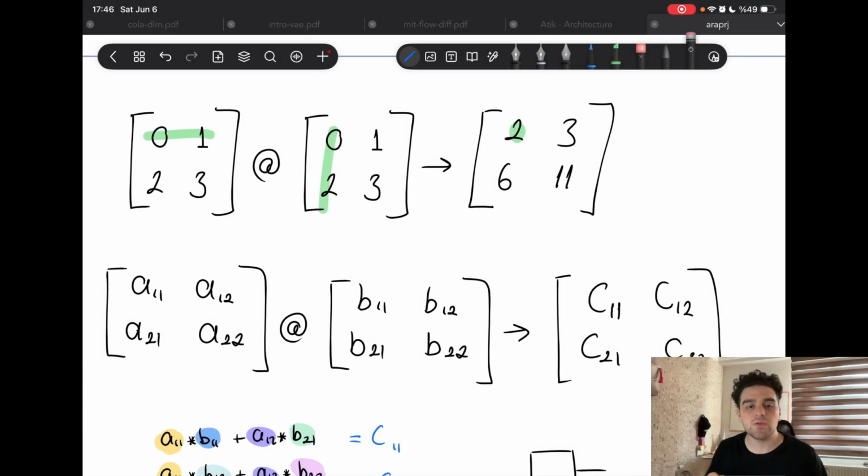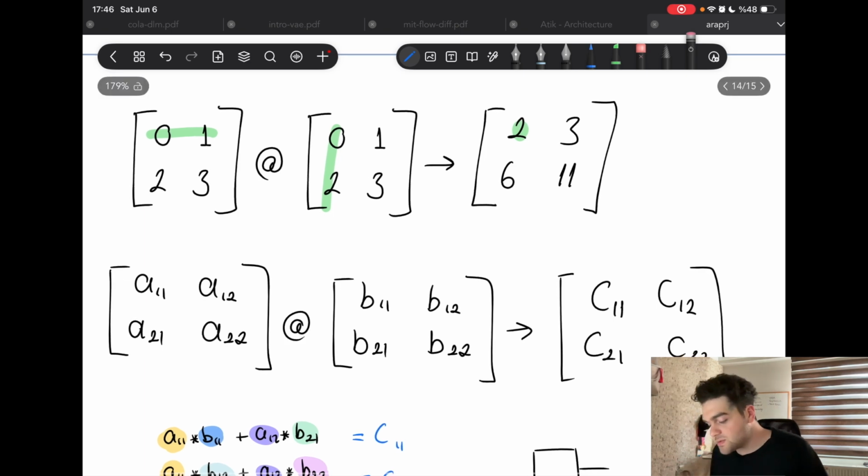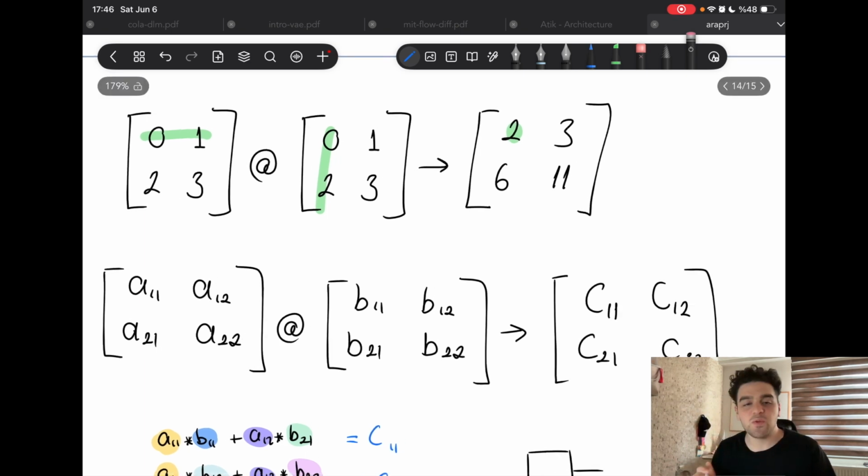See how we are going to develop the matmul data path for our accelerator, and how it is going to solve this matmul problem. How are we going to tile over these matrices and do the computation overall? First, we need to figure out a way to solve this by hand and see how the algorithm proceeds when you solve it on paper.